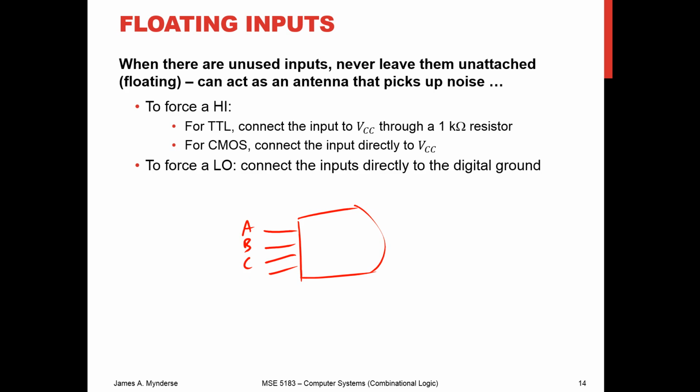What do I do? Well, it's going to act like an antenna, just like the switching case that we considered in lab. And so if you've got this extra input that's just hanging out, don't just let it hang out. That's bad. That's a floating input. So you want to either force it to high or force it to low, depending on what kind of logic signal you want it to have. But if you want to force it low, just connect it to the ground.